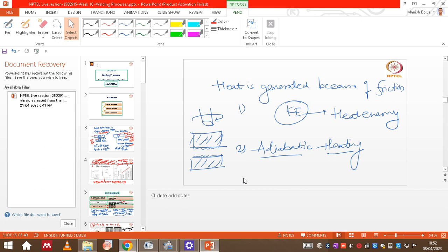Even friction welding processes, friction stir welding processes, can be used on cast material to eliminate the porosity of the material completely. In certain material, if the porosity is very high, like macro porosity is there, in such cases in a single pass it won't fill the complete porosity or complete cavity, but in multi-pass it will modify the cast microstructure completely, and it will completely eliminate the microporosity. It will eliminate the porosity, but the process won't be prone to porosity formation.